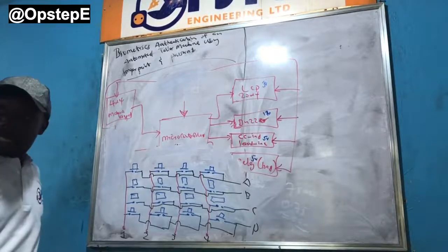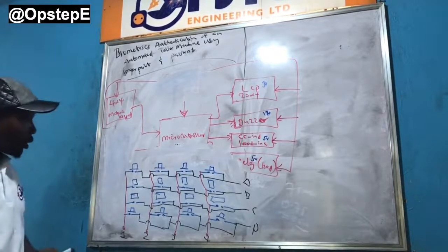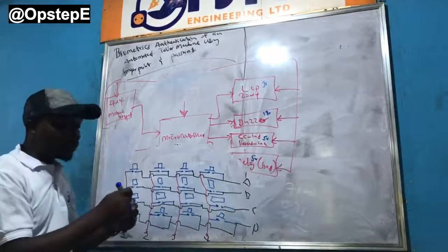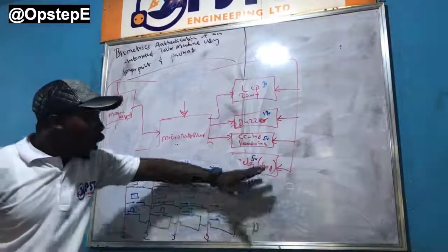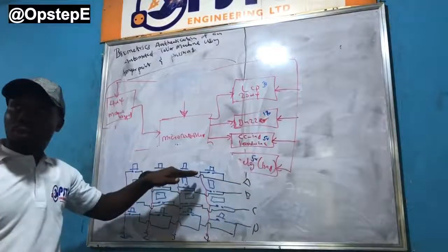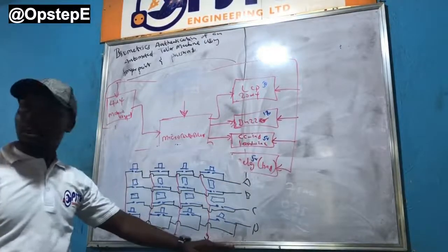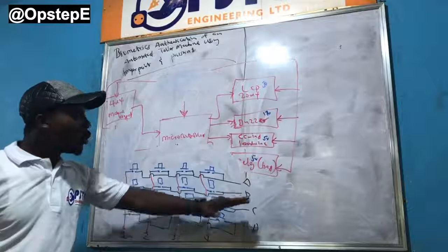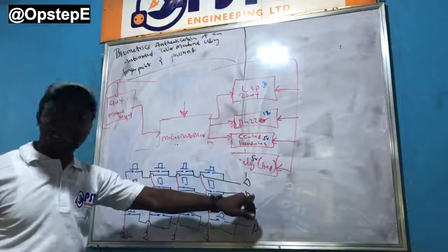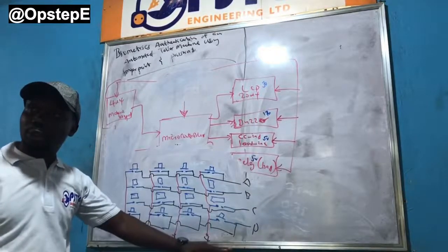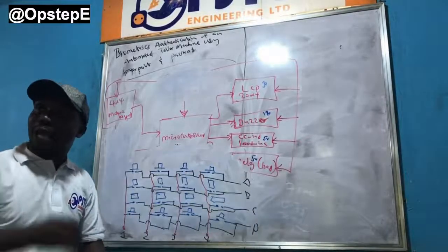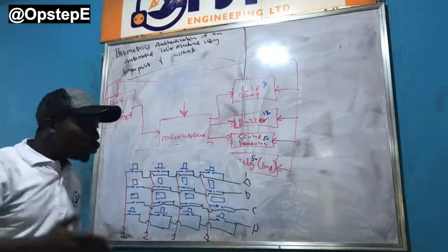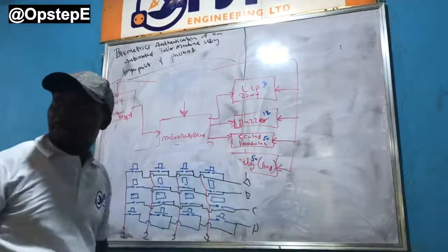Please, are you following how it went? Look at it very well. This will happen, which is what I told you about scanning. At one point, you turn off everyone and send voltage through this one. Then you read this place. If you don't find anyone, put up the voltage and put the signal here and come here to measure, to read. Don't forget, you are only inputting those voltage just one at a time. You are not setting all of them high at the same time.